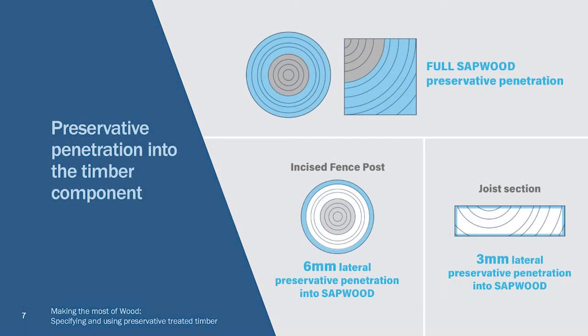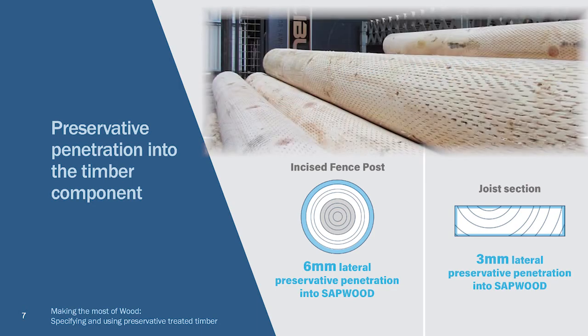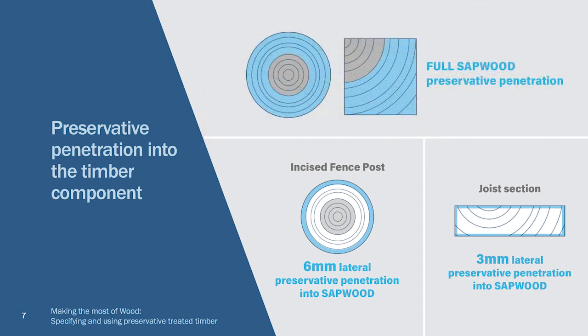Penetration requirements differ depending on whether heartwood material can be distinguished from the sapwood or not. Certain timber species, due to their cell structure, are more difficult to treat. Pressure treatment is therefore the best option to ensure penetration of the treatment reaches the greatest depth possible. Additional techniques such as incising may be required to help these resistant species achieve the penetration requirements, particularly for ground contact applications. Compliance is achieved by meeting penetration requirements to an acceptable quality level.